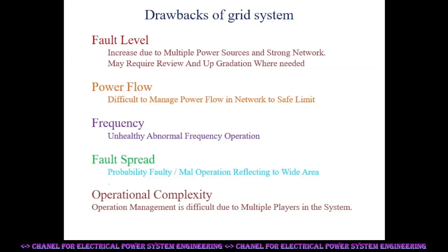However, it may be possible indirectly by restricting power push, by restricting injection from upstream of the sending end of the critically loaded element. Another way is restricting power draw downstream of the receiving end of the critically loaded element. An alternate rude, cruel method is equally risky and not recommended, or very rarely resorted to in extreme emergency. It is diverting power flow through another route by increasing impedance, by switching off the feeding line to the critical element or the exporting line from the critical element. Such indirect operations are very difficult and delayed, particularly when the switching operations required are in a system other than the affected system. The long-term solution for similar critical links is to provide parallel lines using phase shifting transformer or HVDC link.